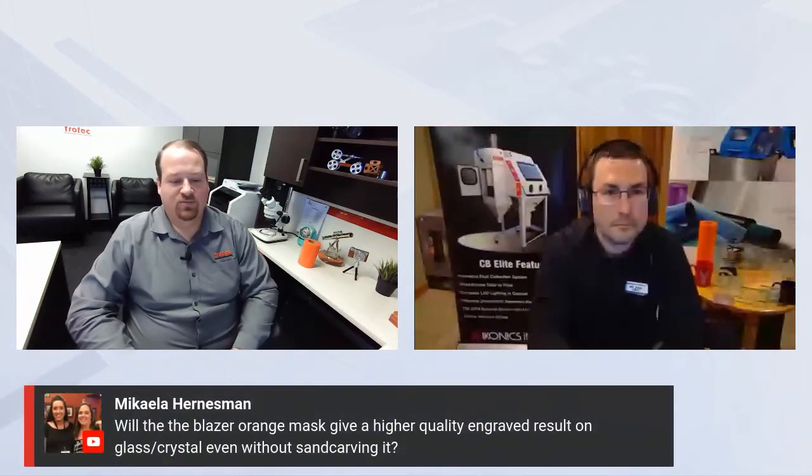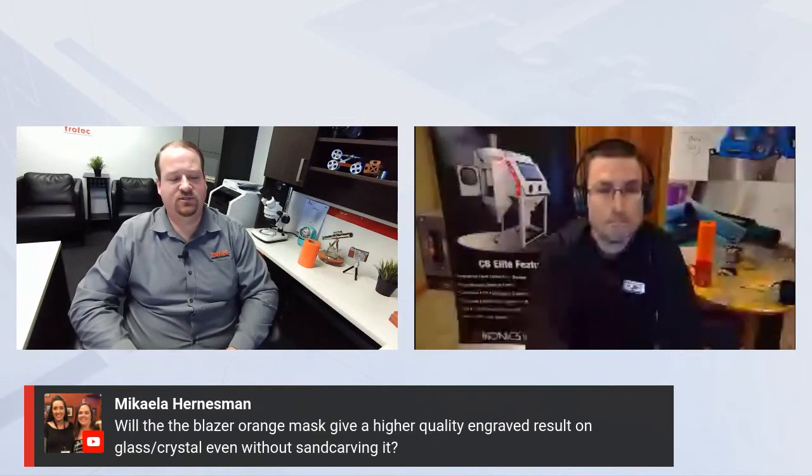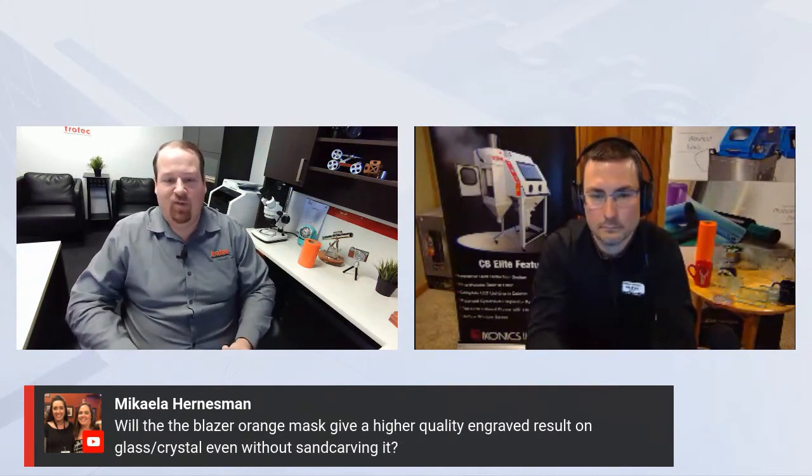All right. Will the Blazer Orange mask give you higher quality engraved results on glass or crystal without sand carving? I think what Michaela is asking is the ability to protect the edges. A lot of times when you laser engrave glass, we run into a phenomenon that looks like a chipping and flaking effect. And so, yes, the answer is yes, the Blazer Orange mask will actually improve the quality because it stabilizes the laser power and absorbs some of that heat, and you're going to see less chipping and flaking when we're just doing a light etching into it.